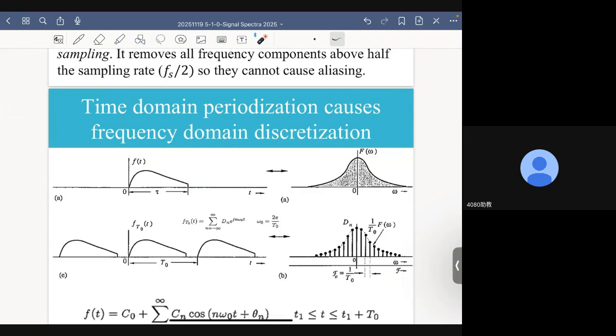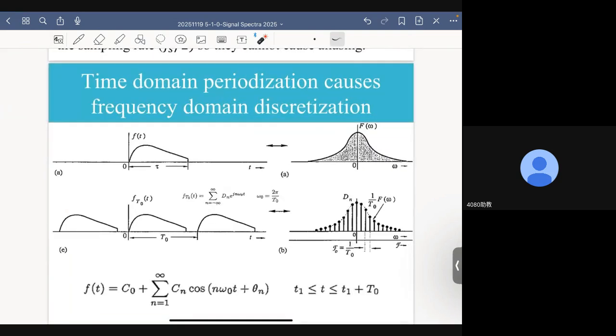And aliasing error pretty much is everywhere. So in an industry standard ADC card, which means if you measure some signals with a sensor, and that signal is an analog signal, and if we want to send it to the computer, you need an ADC card to convert the analog signal into a digital signal. And many of those ADC cards actually come with an anti-aliasing filter whose cutoff frequency you can specify, okay?